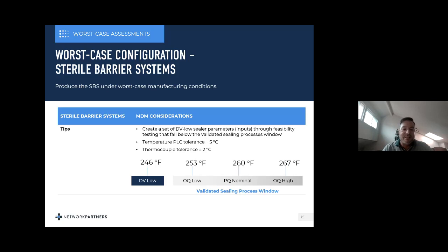You're looking at every aspect, but as you go through the ETO sterilization phase, what really does it do? Because you have breathable material, Tyvek, it's going to stress your seals. So you have time, pressure, moisture, and there's a vacuum pull on it. Really what that is doing is stressing your seals, and the material, the vacuum kind of pulls and then it expands and it aerates from that.